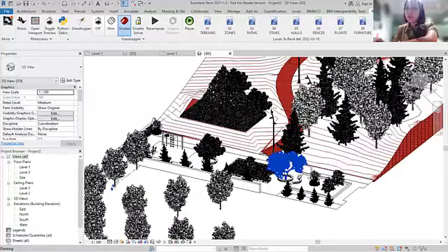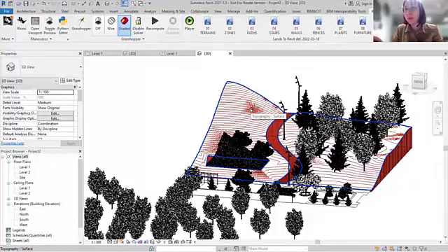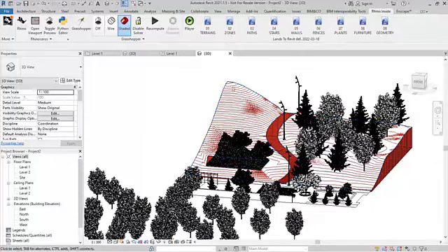Well, there's another question from Chris. Does it work the other way? So if I update, you mean updating the definition? Yes. Whatever modification you do in Rhino, later you update the definition, just click on the definition on top of the Revit environment, and all the model will be updated in Revit too. Yeah, that's what we did with the terrain.